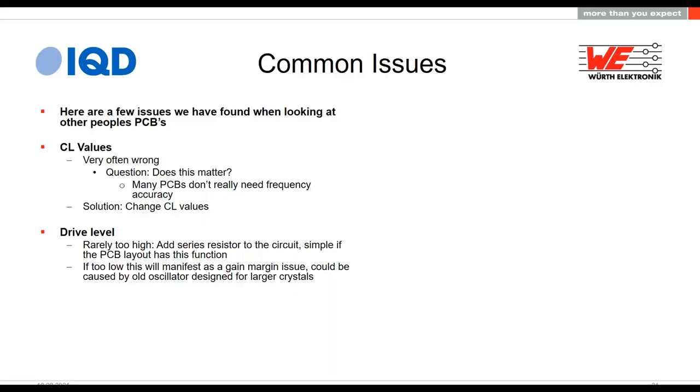And that is quite often caused by using an old oscillator design. As I mentioned before, large crystals have got lower resistance, and that includes the circuits that are within your microprocessor. Sometimes that circuit was originally designed 10 years ago by the IC manufacturer. When they did the assessment of the gain that that circuit has, they were assessing it against larger crystals from that period of time. Nowadays, everything's got smaller, but nobody's really looked at the gain of that microprocessor's amplifier, yeah?